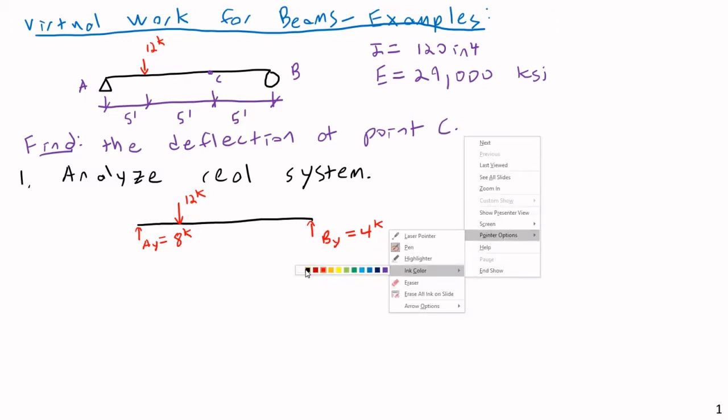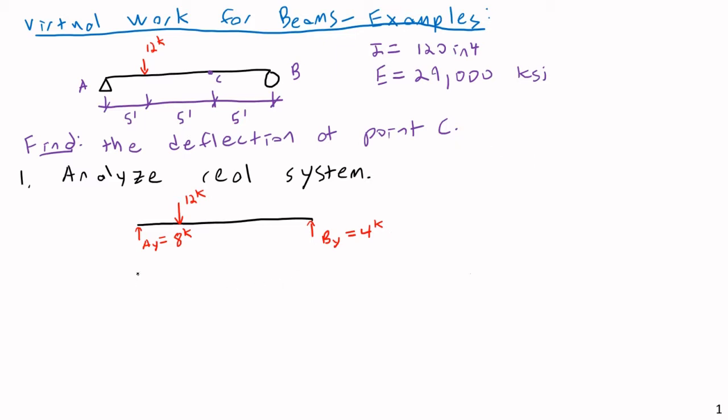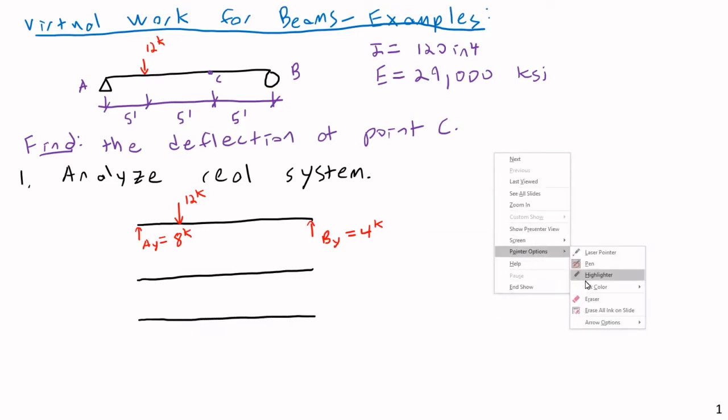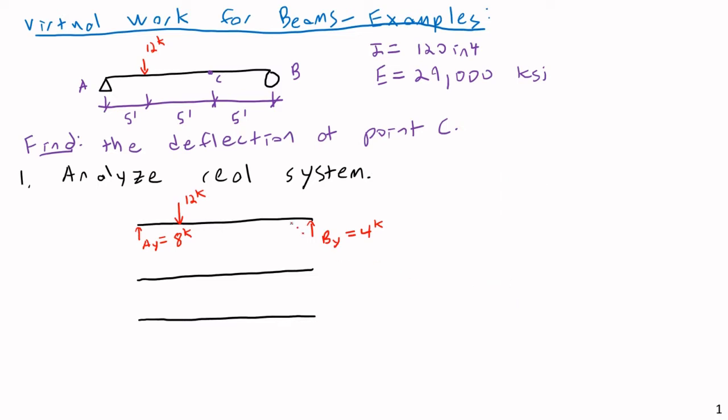Then, in turn, I want to get the shear and moment diagram. Now, what I'm really after is the shear and moment function. If I had any more complex loading than this, I'd probably go ahead and do an integral, but this is simple enough, just a simple point load, that I think I'm just going to go ahead and do the diagrams by inspection and then get the equation from the final moment diagram very easily. So here, our shear diagram. Again, this is going to be our V in kips, and our moment in kip feet.